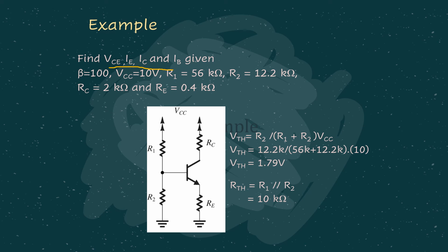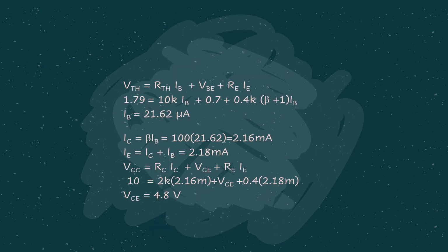So you know how to identify the voltage divider biasing circuit by looking at the number of resistors. Since we are having R1 and R2 like this, we know it's voltage divider biasing. So no choice, we have to do the Thevenin equivalent circuit. We have to find RTH and then VTH. Then from there we can do the KVL equation, because it's already replaced in the input side.